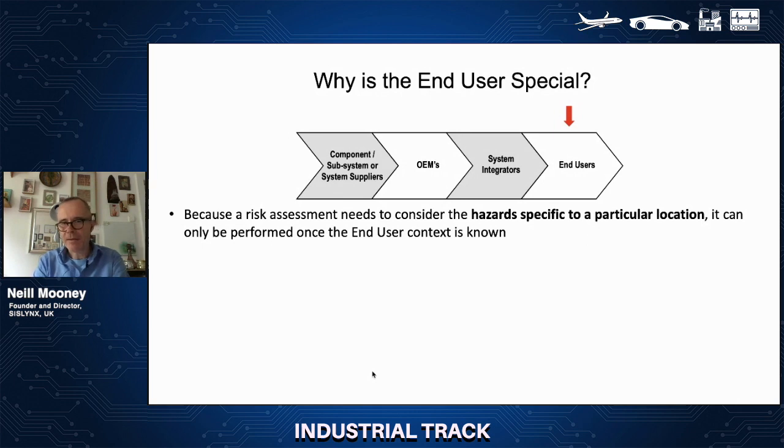But the risk is frequency times the consequence. So the consequence would be measured in terms of the harm to operators, in terms of loss of life or injury, or it could be measured in terms of loss of equipment. So there'll be a dollar value associated to the harm. But all of these types of calculations depend on understanding which operators are there, when are they there, what's the distribution, how is equipment located relative to the specific hazard that you're looking to control with the SIS.